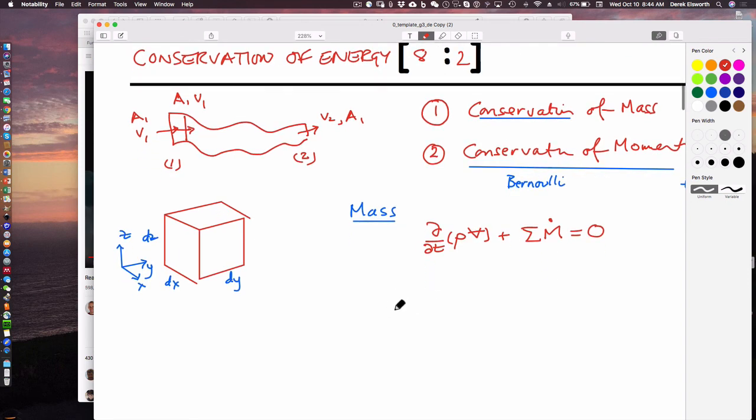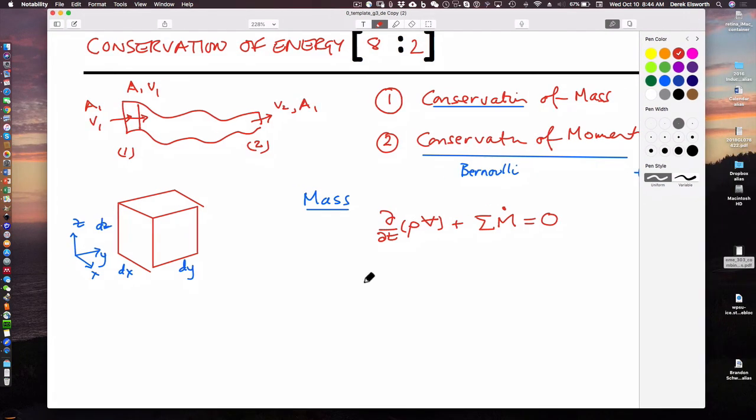And typically we've written this out in longhand on the left hand side to have two parts. Density times the rate of change of volume plus volume times the rate of change of density plus mass flow rates are equal to 0. And if the control volume doesn't change, then this is equal to 0, and we have these two parts. We have the mass conservation part, and we have the accumulation part. This just says how quickly it accumulates. This says mass in equals mass out, then it's equal to 0. If there's some net accumulation, because fluid goes in and less fluid comes out than goes in, then its density has to change, even though the volume is the same. And so this is the accumulation part.